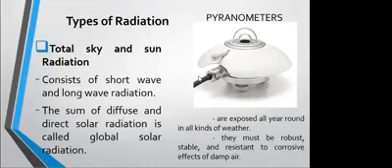So the global radiation is measured with pyranometers, and the direct radiation, which we discussed earlier, is measured with the pyrheliometer from the previous slide. The device uses two types of sensors, the thermal and the photovoltaic.